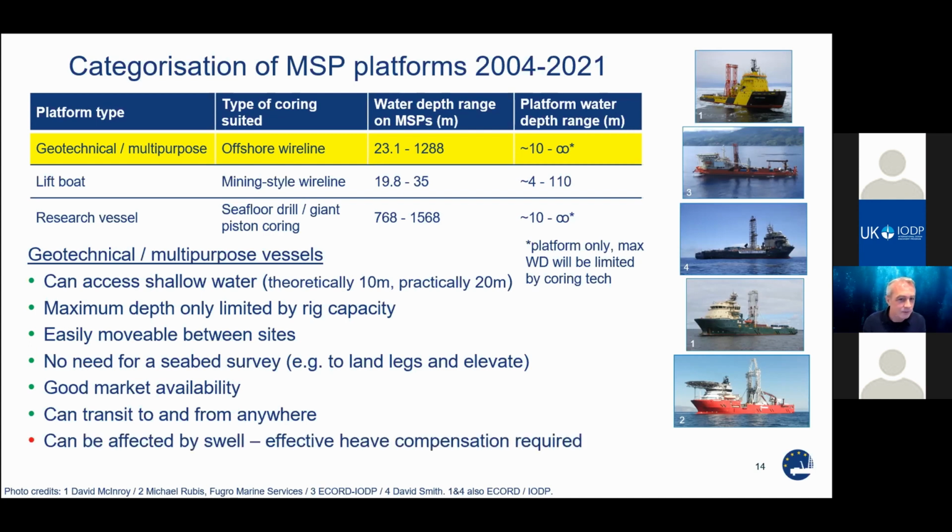Disadvantages are that these types of vessels can be affected by swell, so we must rely on effective heave compensation for the installed coring systems. And even the best systems still convey some movement to the bottom hole assembly at the base of the borehole, and that can affect core recovery. And finally, these vessels being in constant dynamic positioning, it takes extra fuel, which has a cost implication. And they can be noisy, which can be fatiguing for people working on board.